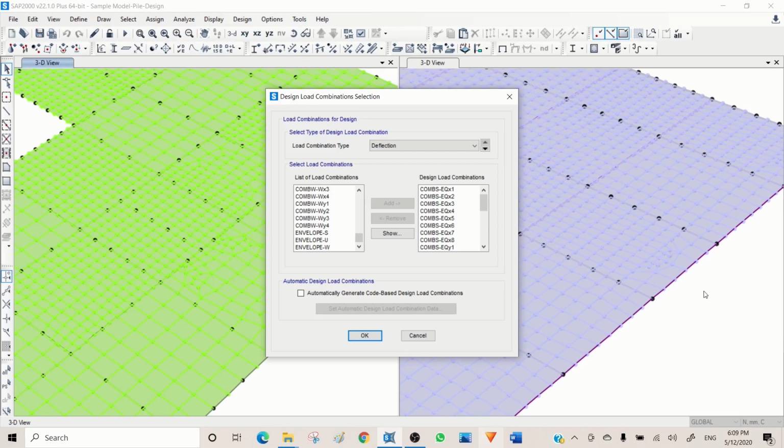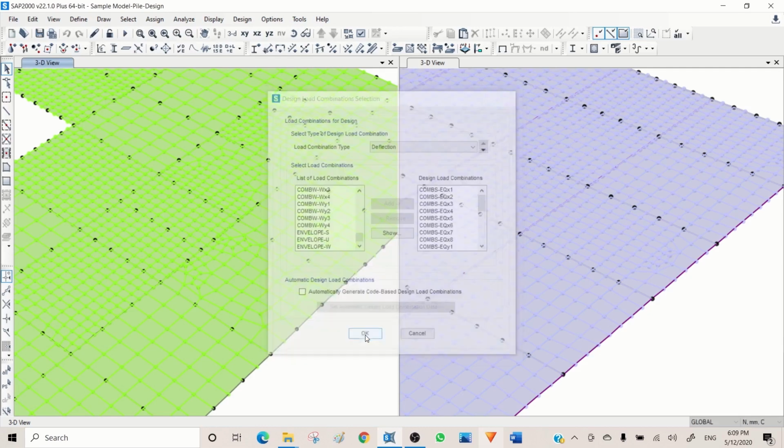If you have 10 different load cases of wind, but you want to combine them, for example, you have a roof wind load, you have external wall wind load, which is leeward and windward and side, and you have internal pressure, you want to see all three in one combination. SAP doesn't understand that. SAP adds them one by one: one for internal, one for external, one for roof. And that's how it creates the load combinations. You can try it yourself just to save time. I'm not going through this, but this is how it's happening. So I'm using this and I press OK.